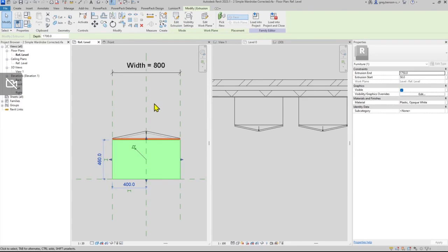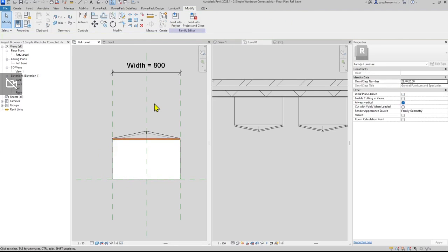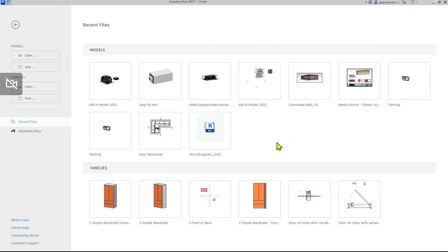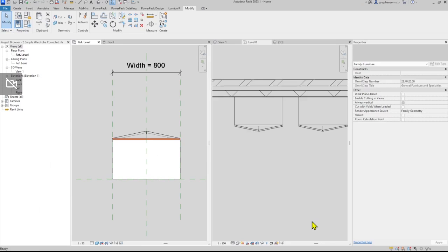Last two quick tips, because unfortunately we are out of time. When you're modeling and making parametric models especially, every time you add something new, test it. It's what we call flexing the model. Okay, if I go ahead and open up some other example, let's have a look at this one.